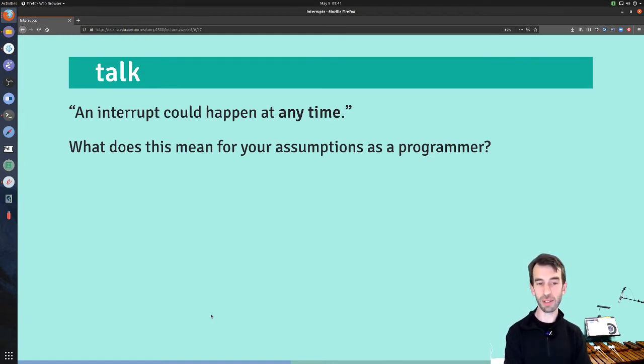In interrupts, you're certainly not in control of some of the interrupt handlers. And even when you are in control, as in you have written them yourself, you're not in control of when they occur. That means you don't have the ability to do any setup for your interrupts. It's just a function which is getting called by someone else. You might have been in the middle of some important work, all your registers are full of important information, and then this function just suddenly gets called.